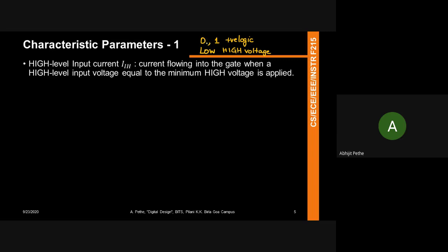So when you do active low circuits, remember a decoder, you can have an enable that is active high or an enable that is active low. When I say there's an active low enable, it means that the chip will work only when the enable signal goes low. It is normally shown with a bubbled input, whereas positive logic will not have a bubble; it would just be a standard connection into the chip.